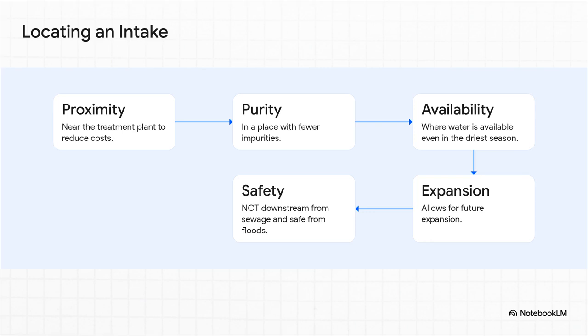Now, where you put this thing is a huge deal. It's not as simple as just dropping it in the water. You've got to think about a bunch of factors. You want it close to the treatment plant to save money on pipes, right? But you also want it where the water is cleanest. And you need to make sure it won't run dry in a drought or get washed away in a flood. And definitely not downstream from a sewage plant. It's a real balancing act, a classic engineering problem.